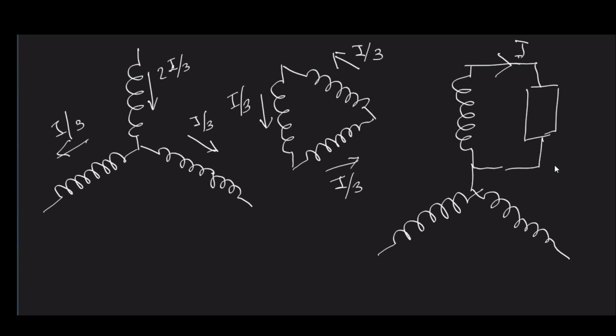However, you can see that these I3 have corresponding terms, so they are doing that kind of load balancing, and no such high voltage will appear across your secondary terminal due to the presence of this tertiary.